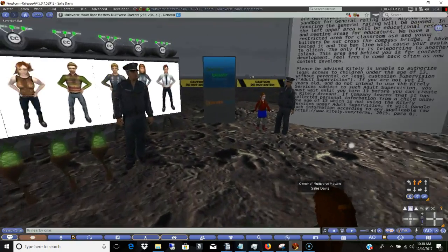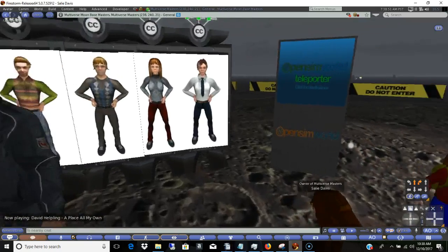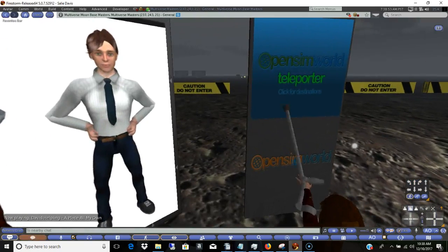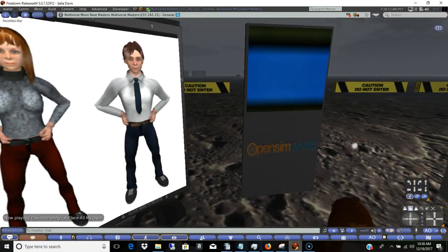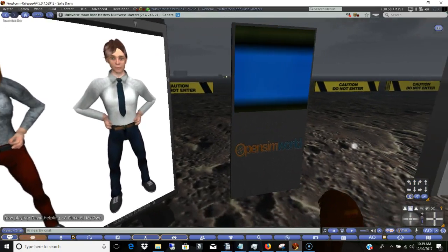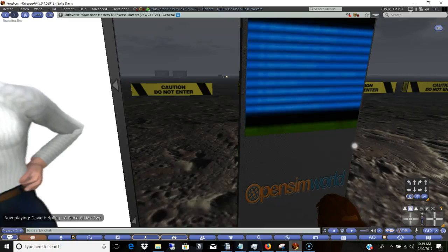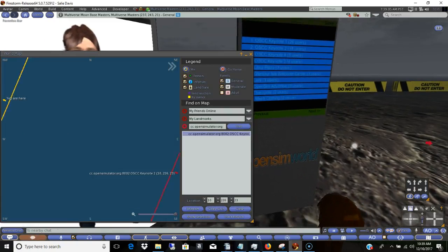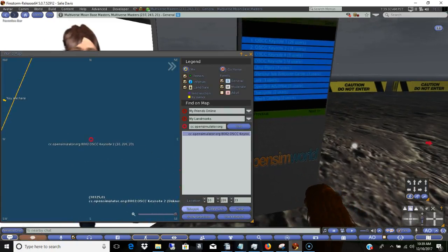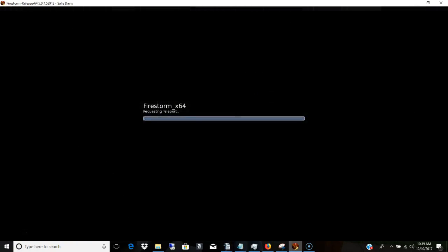So once we've got that OR file read in and we've got our OR underbar unpacked material, you just select the file menu again and then say convert data, and it's going to convert the whole thing. It runs pretty quick, but it may take a couple of minutes if you've got tens of thousands of objects, but that's going to then create your DAE underbar with a name, and your converted content will be in that.